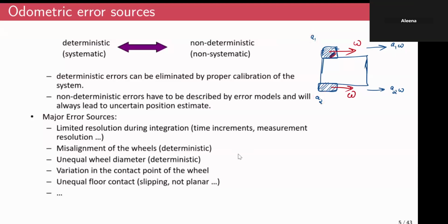By giving these constant inputs, we expect the robot to move in a straight line. But due to the change in radius, the robot would move in a curved manner, depending on the size of the wheel radius, as opposed to a straight line.